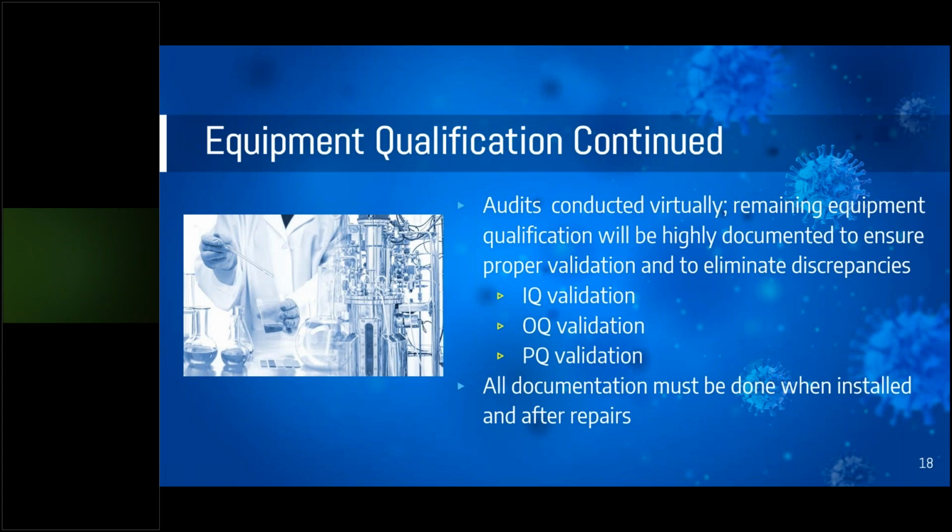So how exactly are we going to do this? Well, again, we're going to have to take it remotely and do things offline. As just mentioned, the main aspects of your process qualification will be maintained. So your installation qualification, making sure everything is in the right place, there's enough space around, has the proper software, and so on. Your operation qualification, ensuring everything is properly calibrated, has the proper alarms, the equipment and instrumentation is all there, the valving does what it's supposed to do.